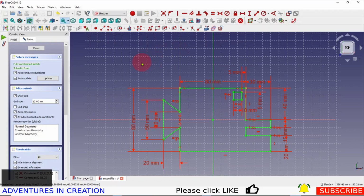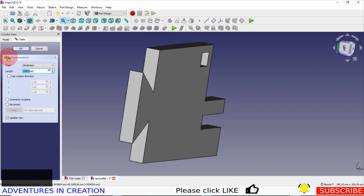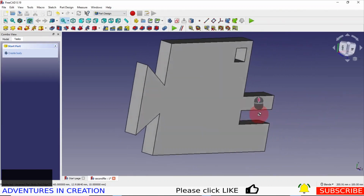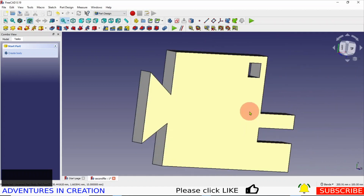Now, of course, in my sketch, it's 10 millimeters thick. So we're going to close this sketch, and then we're going to pad the sketch, and it automatically goes to 10 millimeters thick, and we say OK. And now we have a model of that part, fully constrained, that is 10 millimeters thick.